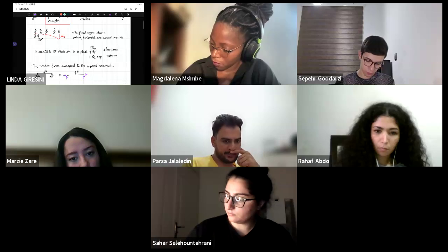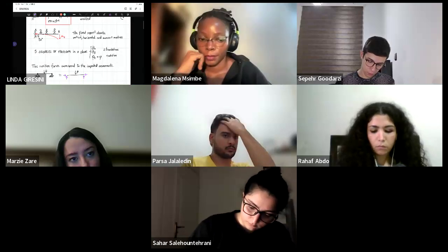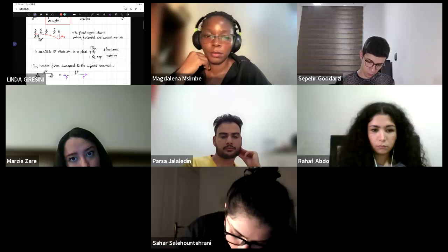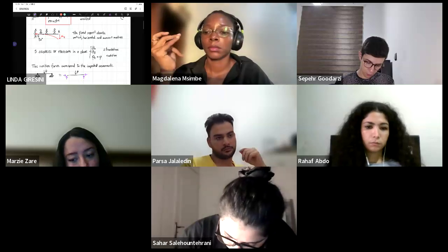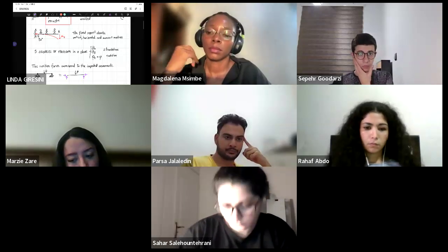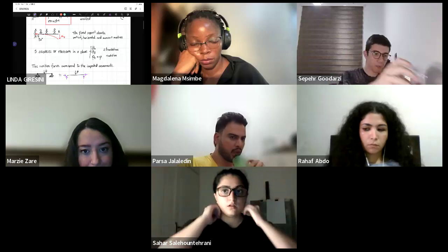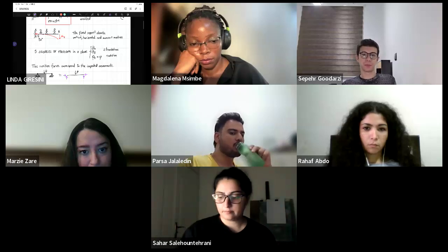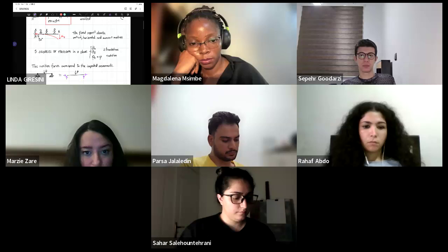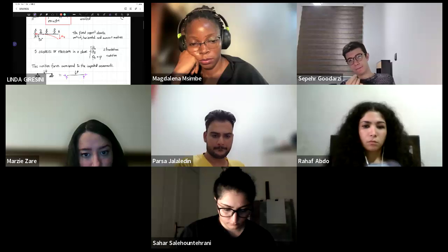Thank you also who answered from home, okay? So the movements which are impeded, for example for the hinge, the vertical and the horizontal translations, translate, sorry for the play of words, into the corresponding reaction forces. Because if I have to impede a movement in horizontal direction, I will have a reaction force in the same direction. Otherwise, the movement cannot be impeded.